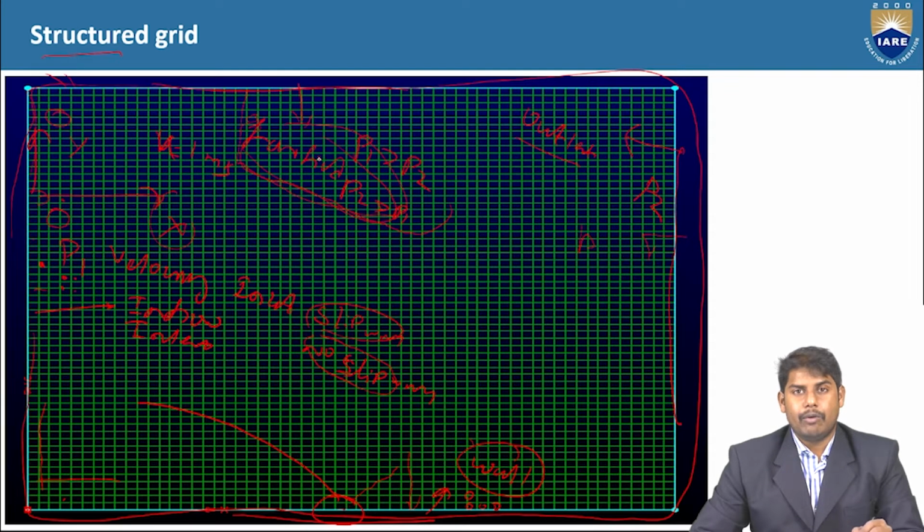So the major important thing that we have to take is how much length or how much height we need to take so that this region is undisturbed. Okay, and one important thing is that you need to capture everything, and you need to actually see that nothing is missing while doing the CFD analysis.